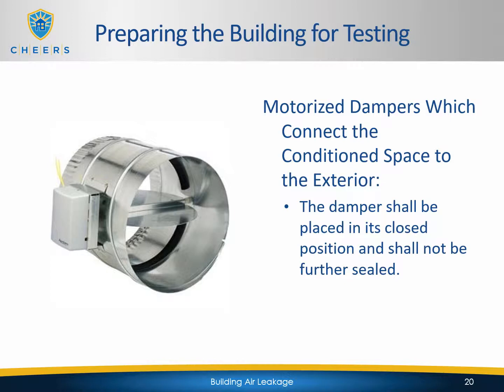For motorized dampers which connect the conditioned space to the exterior, the damper shall be placed in its closed position and shall not be further sealed. So you're going to close it and you're not going to seal it any further.